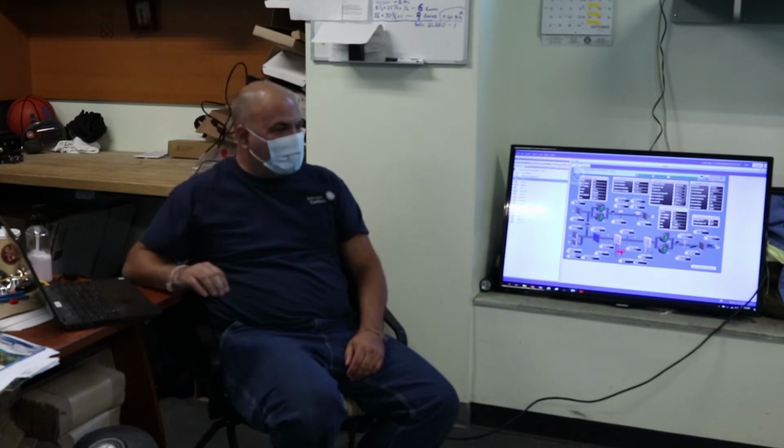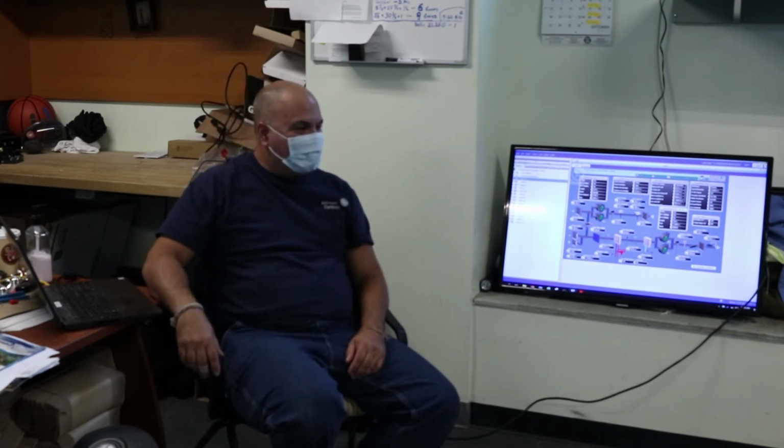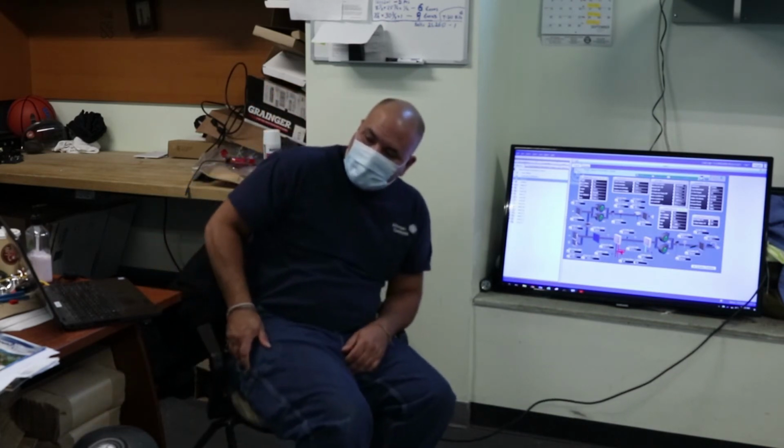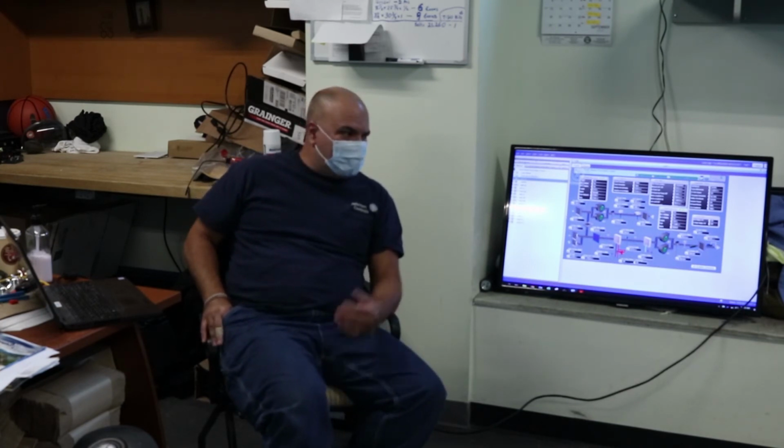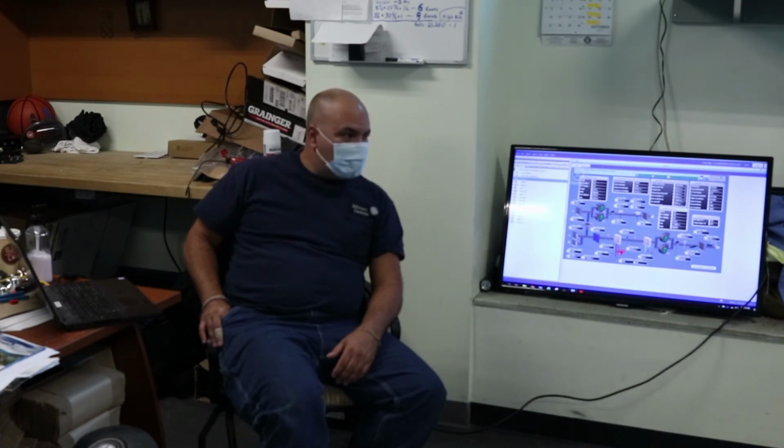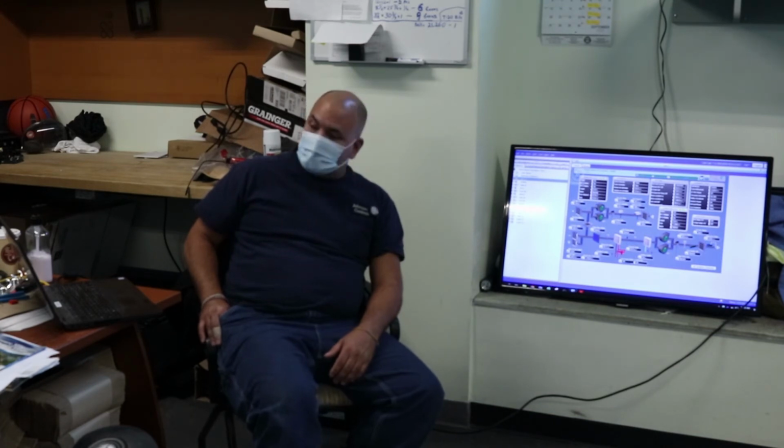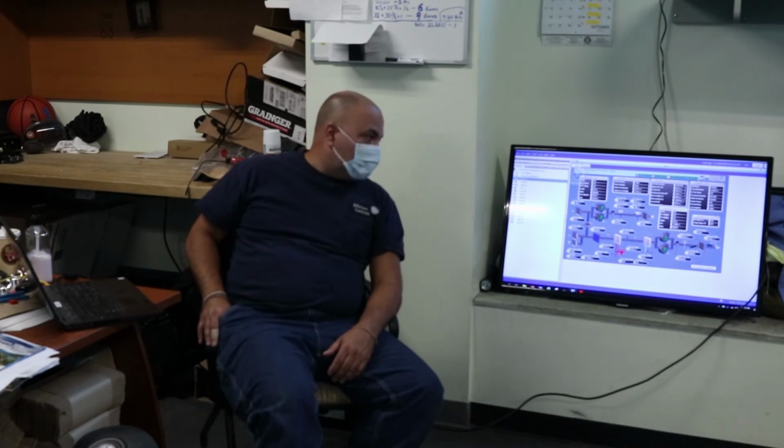What about the boiler plant makeup air units? The MAUs, do you have a question? Basically they just give them an enable point and then they pretty much run on their own. They run based on when the outside air temperature drops below. Yeah, they operate off their own little PLCs that are inside. All they do is enable, that's all they do. You can always put a wire nut on there if they give us an issue. You know how to change set point on a boiler? Yeah, yep. It's pretty easy to do once you're on the screen. So, yeah, we got that.